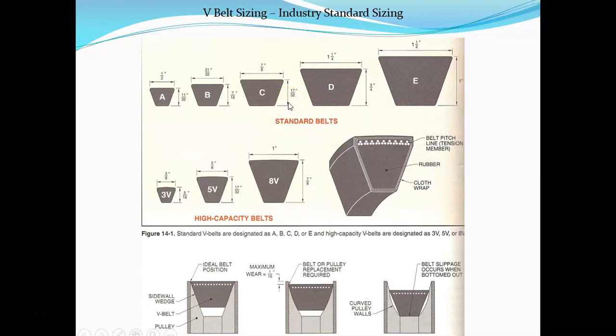So manufacturers are going to make these to these industry standards. Let's look at, I want to really quickly mention, the strength of a belt. Notice there's a lot of material here in the belt. There's an outer cover, which is really just to protect the inner part. So you have a lot of filler material. It's rubber. The strength of the belt is coming from these fiber cores that are along the top, and you'll see